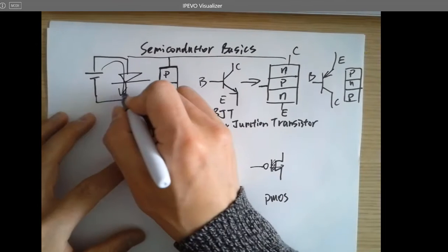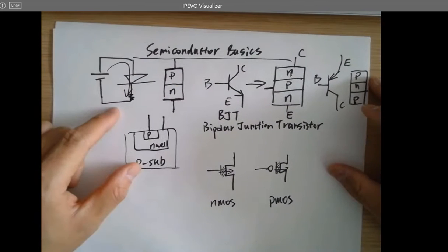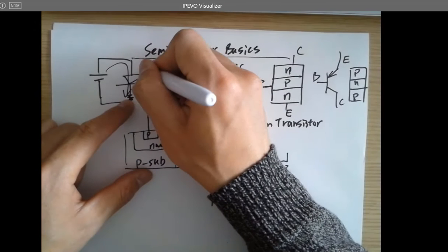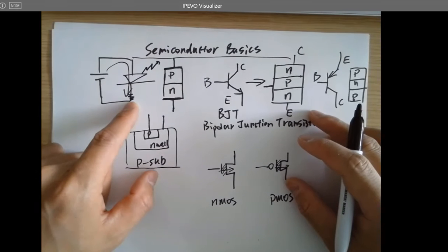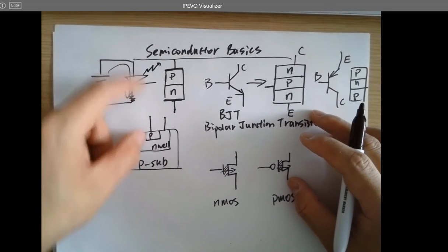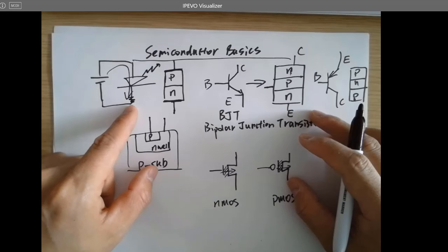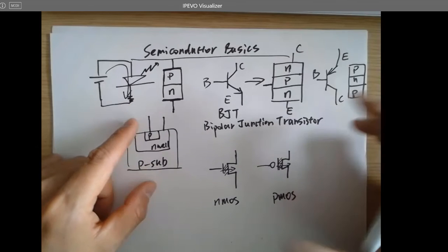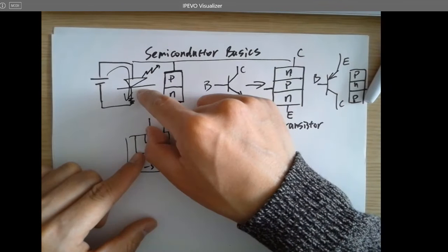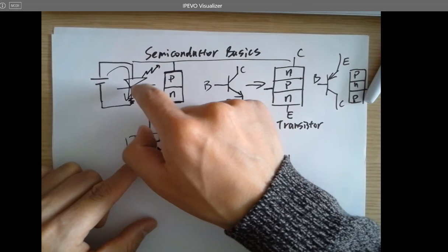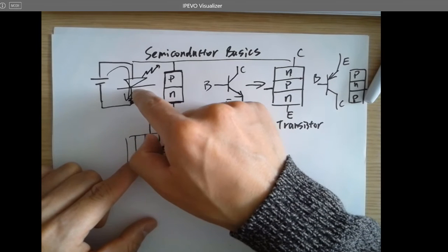You probably need a resistor. You have done this in microcontrollers, because if this is the LED, it's a different type of diode. You have to use a little 220 ohms resistor to protect the diode because the current is going to be too high and burn the LED very quickly. Right, so you'll know that if you have a positive potential being shorted to the diode like this, it's called forward biased, then current is going to flow into the circuit.